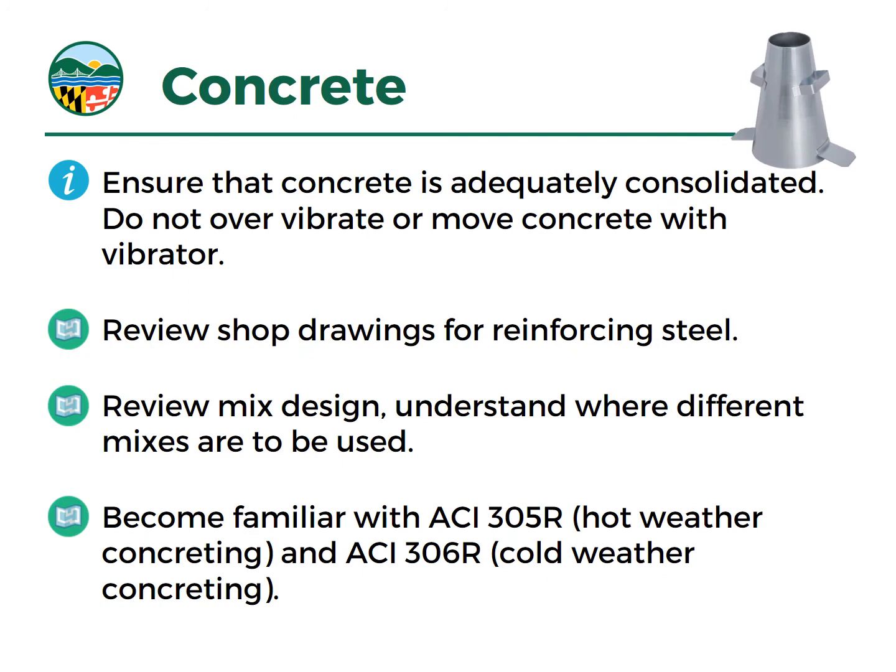You want to make sure that the concrete is adequately consolidated. You don't want to over vibrate or move the concrete with the vibrator because you can get segregation and poor quality. Again, I mentioned the inspector should review the shop drawings for reinforcing steel, make sure they understand them clearly, and understand the mix designs and where different mixes are to be used. It's a real shame, and I've seen it happen before, when you've got a big project going on with multiple concrete mixes at multiple locations, and you pour the wrong mix in the wrong location. That causes all sorts of headache because you have to rip out multiple portions of concrete and redo the work, and it's no good for anybody.